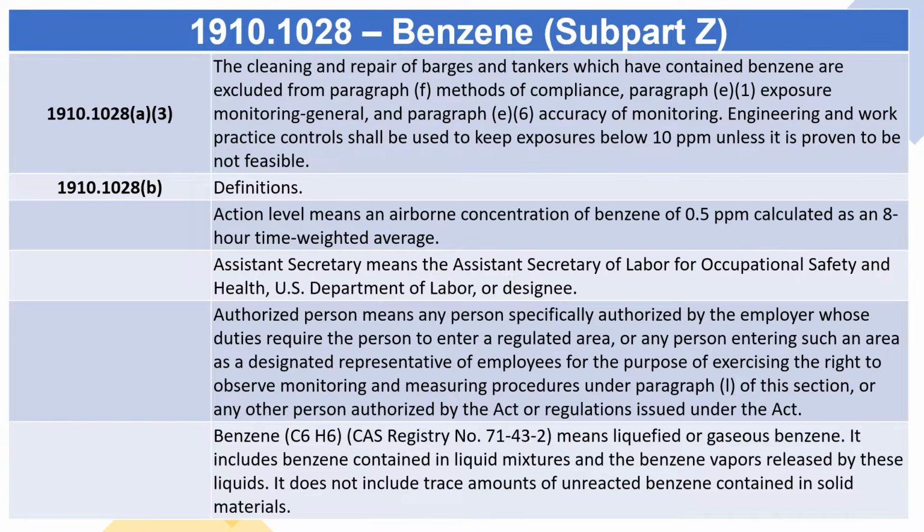1910.1028(a)(3), the cleaning and repair of barges and tankers which have contained benzene are excluded from paragraph (f), methods of compliance, paragraph (e)(1), exposure monitoring general, and paragraph (e)(6), accuracy of monitoring. Engineering and work practice controls shall be used to keep exposures below 10 ppm unless it is proven to be not feasible.